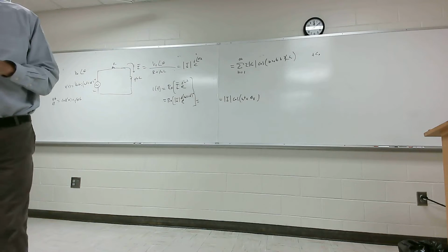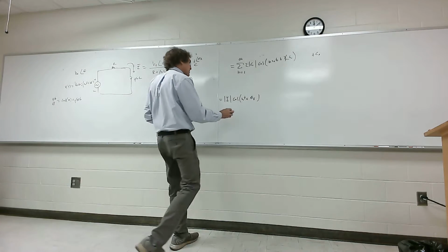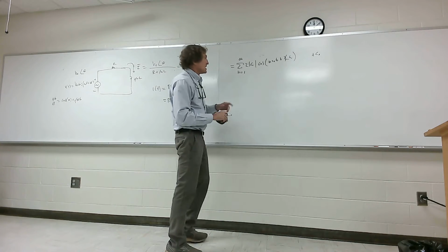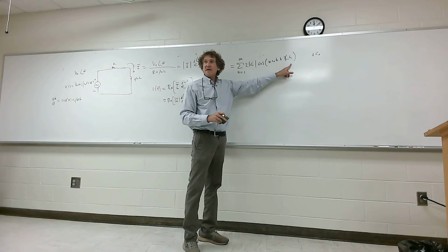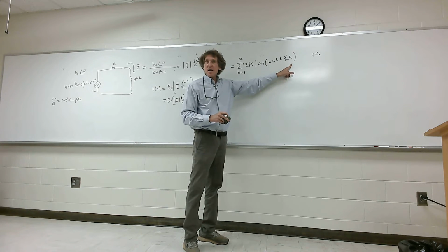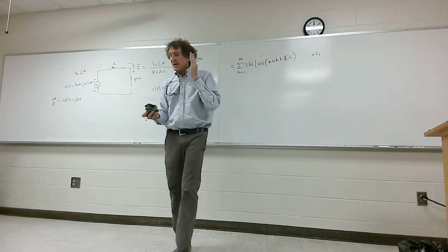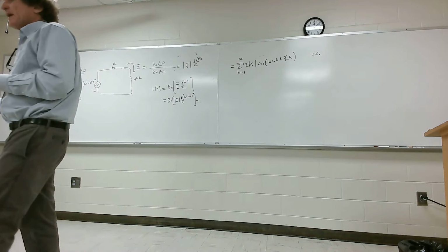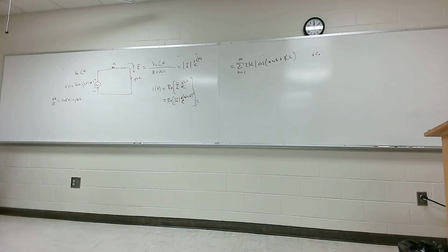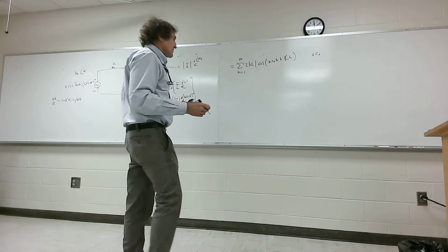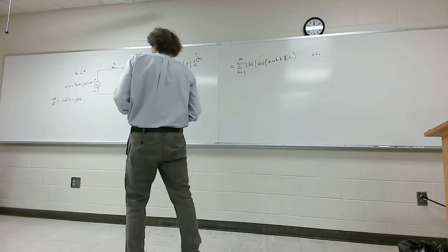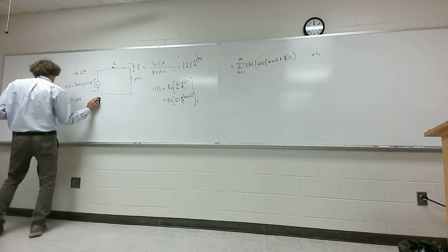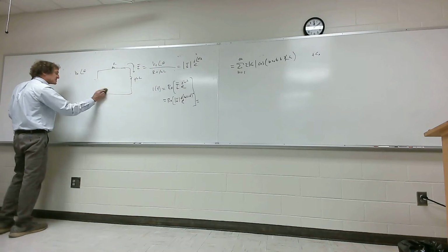Now, why did I do that over here? Or why am I interested in this? You see how each one of these is a phasor? Can you all see that, class? Magnitude and phase. It's at each different harmonic. You would have to evaluate the circuit impedances at n omega, not omega. Then you would find, if you had a system, and this is really the last part on this part of it, and I'll show you how to do the analysis of frequency.